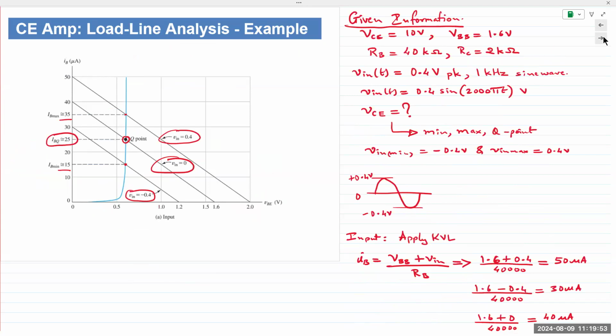You can manufacture the same transistor, same time, same temperature, same machine, everything's the same. It's just not possible to get the exact same beta values. So there's a range of beta values provided by the transistor, even if you have the exact same model. Okay, so the beta values might be from 200 to 300, or 150 to 250, and so on and so forth. Typically, if you pick two transistors from the same model family, there might be some variation, not a whole lot.